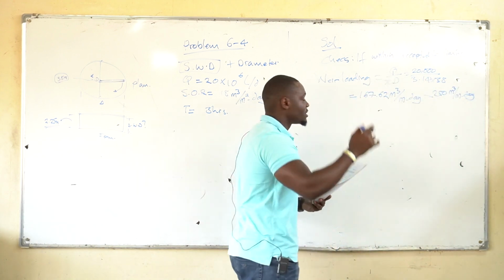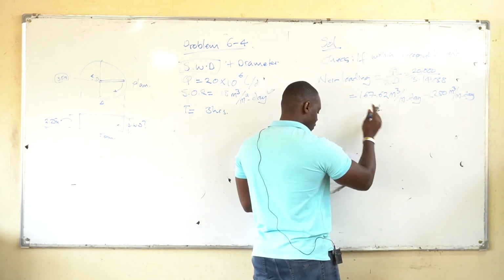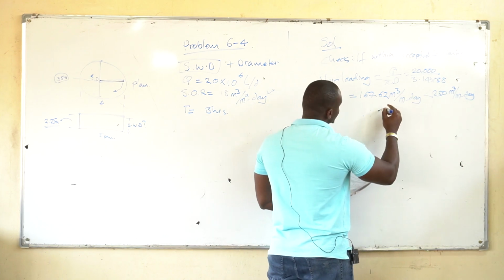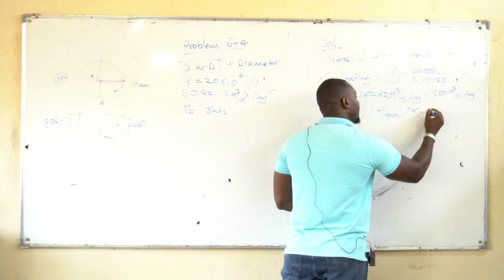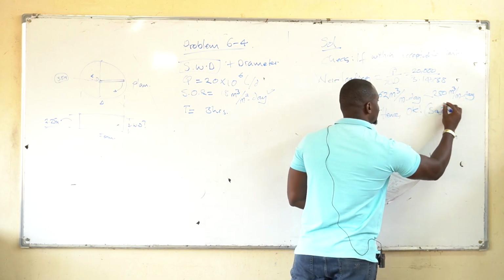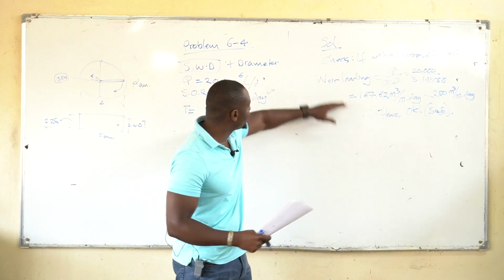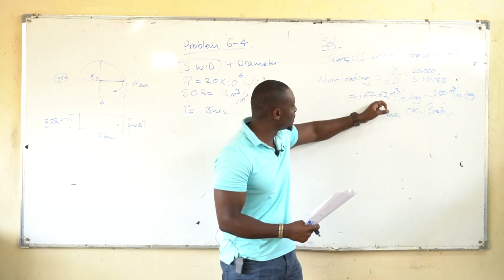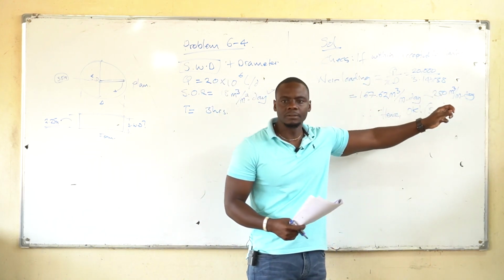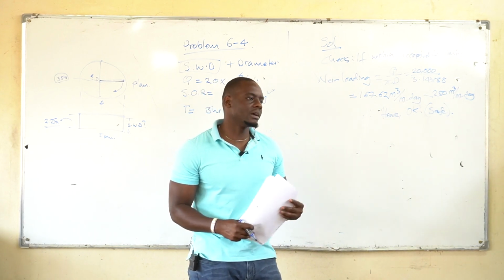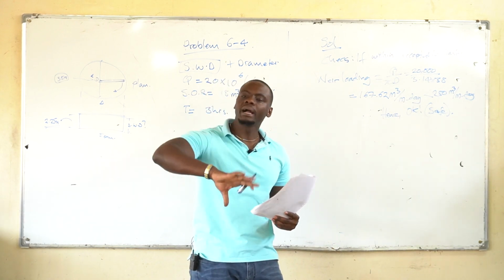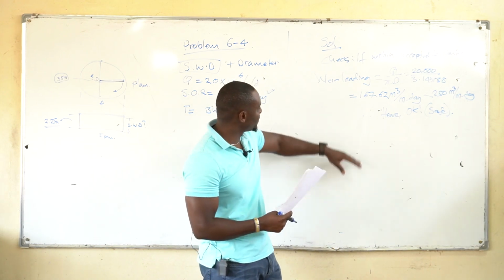Then you can deduce as the engineer to say, hence, okay, or safe. But if you found that your wear loading was more than the 250, then you state that your structure is not fine, and the designer should go back and just rework on the aspects.